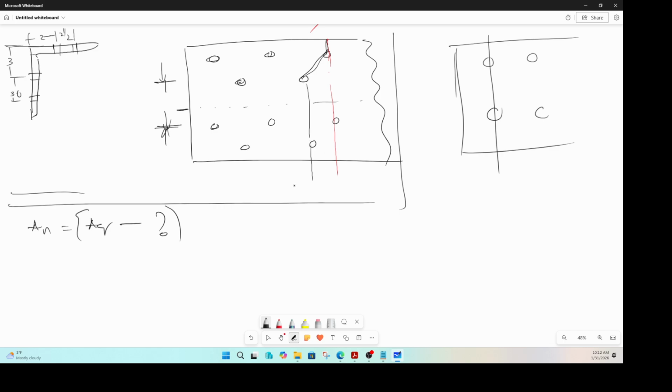And the main parameters that come into play is something called the gauge. Sorry, this is the S value, and then the gauge distance of those bolt holes, meaning from here to here, that is one gauge distance. From here to here is the other gauge distance. From here to there is another gauge distance, right? So we need to know what S is, what g is, and how we can calculate the A_net for a staggered connection. This is what we'll discuss next time.